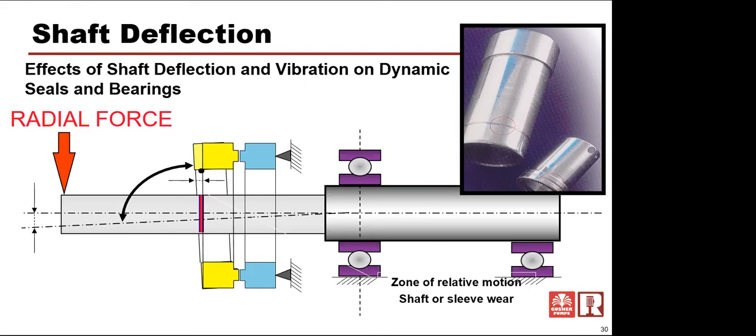A ball bearing can accommodate itself if the force is fairly consistent. But generally, when we're out on the curve or at deadhead, it is fluctuating, and not only do we get a radial force, but quite often there's a thrust force that changes as well.